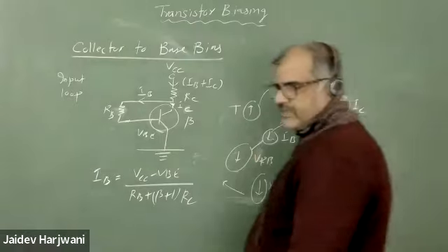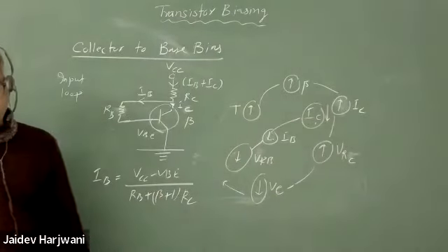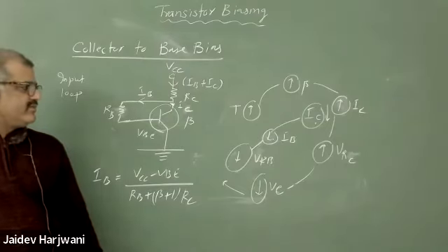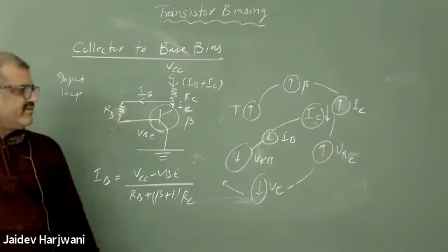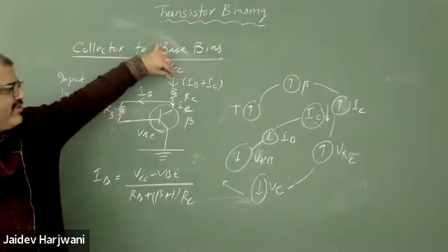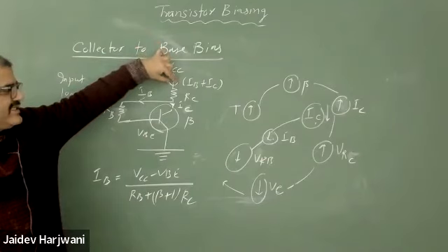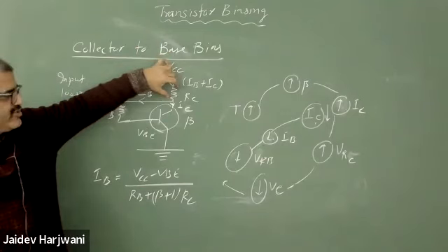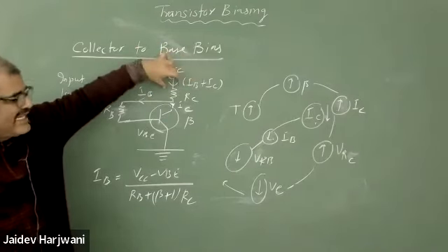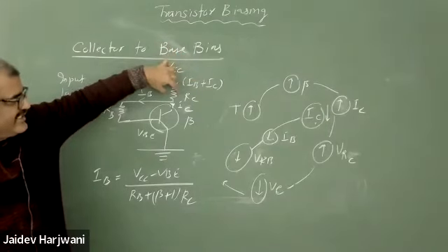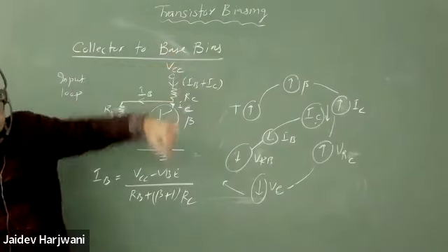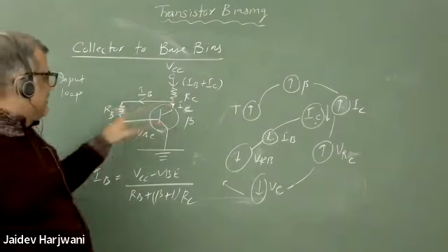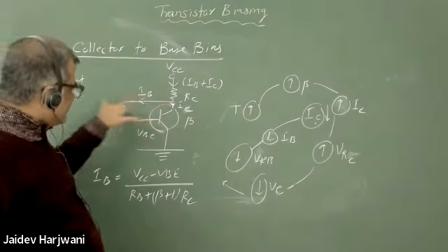Yes, tell me now. Sir, VRC is increasing, then VC is decreasing. Yes, VC. Some voltage is there. Now if IC increases, this voltage drop will increase obviously, because IB is negligible compared to IC, so mainly IC is flowing. So this voltage drop is increasing, that means this point will decrease, right? This point voltage decreasing means your VRB is decreasing, so less current will flow here.